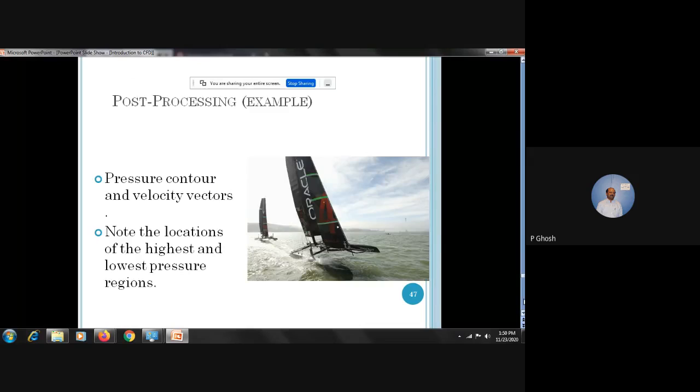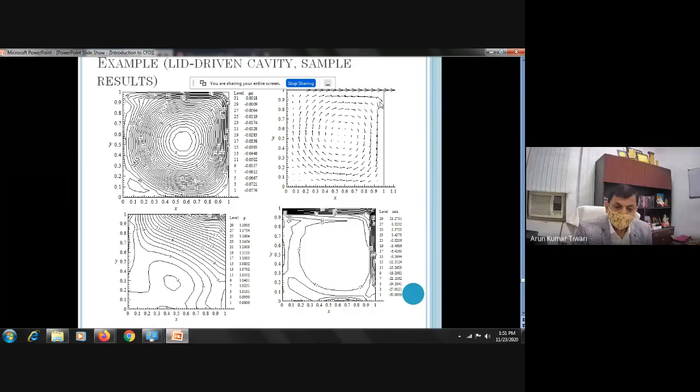Now you get the results. You can give the pressure contours and different velocities in different cases, etc. Another plot you may not be familiar with is called a vector plot, which is basically, for a two-dimensional plane, the magnitude root over u square plus v square, where u is the x directional velocity and v is the y directional velocity. So this is a vector plot.